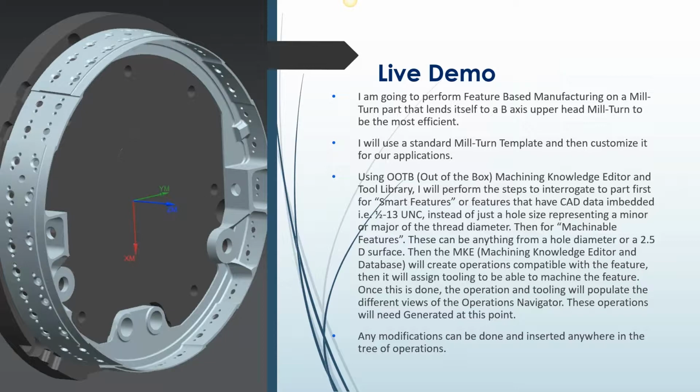Once all that's done, the operation and the tooling will populate into the different views of the Operation Navigator, and then you just generate the operation at that point. And then any modifications that need to be done, you can insert anywhere in the tree of operations.